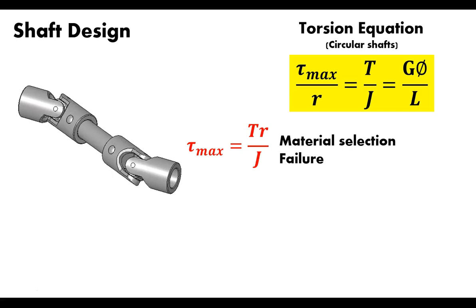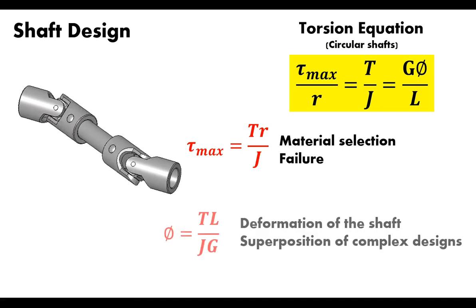So this particular equation is really important to understand, and you can see the benefits of a hollow shaft compared to a solid one. Of course, a solid shaft with the same outer diameter will have somewhat more resistance to a torsional load, so resistance to being twisted. But a hollow shaft will actually have less weight. So this could become an important design factor that you're concerned with, and through the polar moment of inertia, you can actually see that in your design.